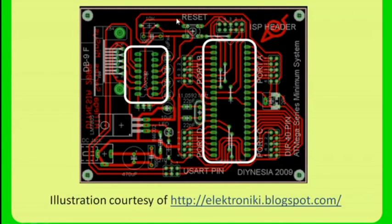This is called a printed circuit because all of these etchings started as a solid plate of copper on some plastic sort of a base and photographically exposed with a chemical that resists the etching of acid, so that when placed in an acid bath, only these parts of the original plate remain, forming conductors as well as the physical means by which a chip is attached to this board.